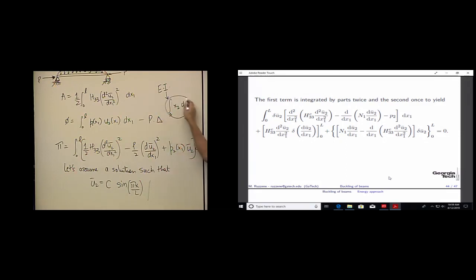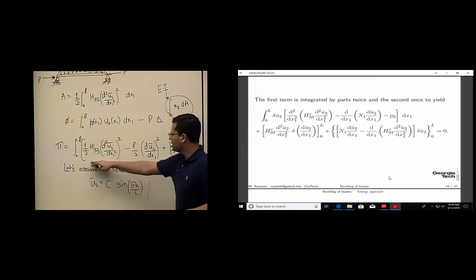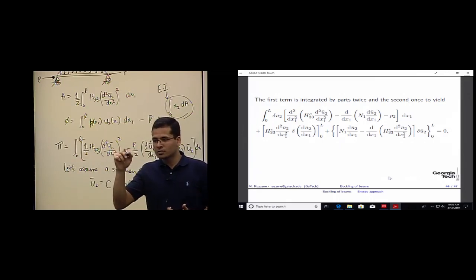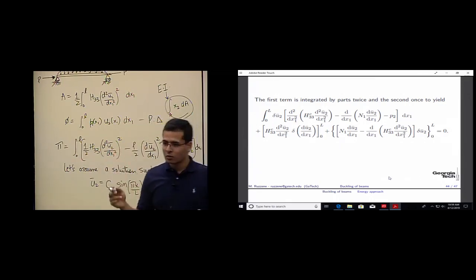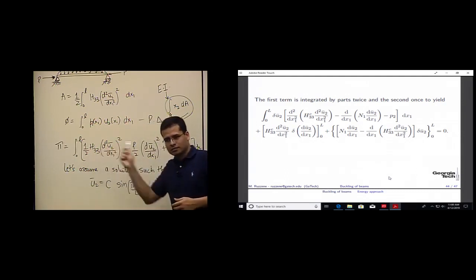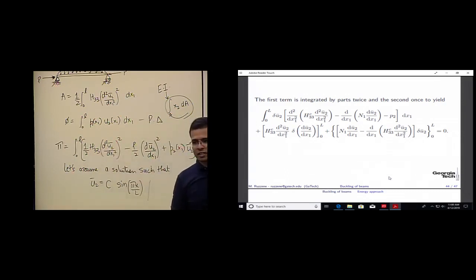So this term will no longer be there because you will have different powers here. So you would have to take a step back and rederive this expression using the volumetric energy. So the integral of 1/2 sigma times epsilon dV will give you another expression here, because you can no longer define H33.